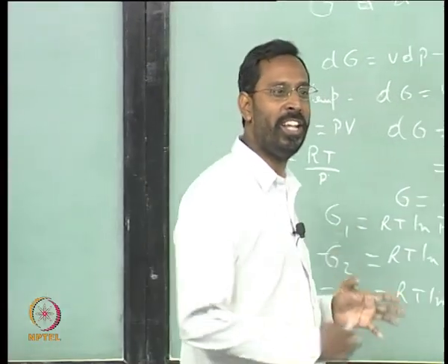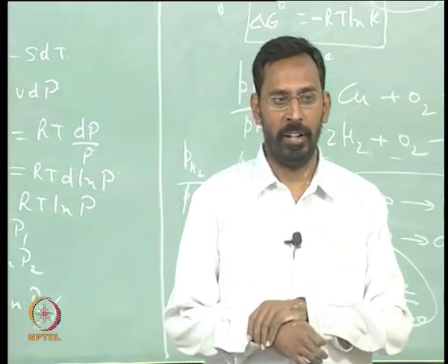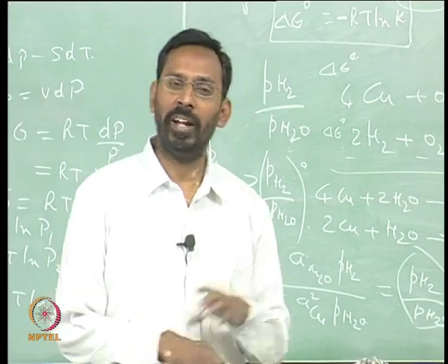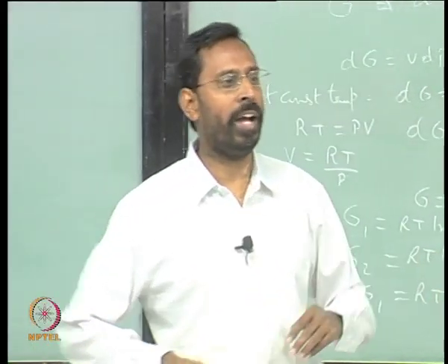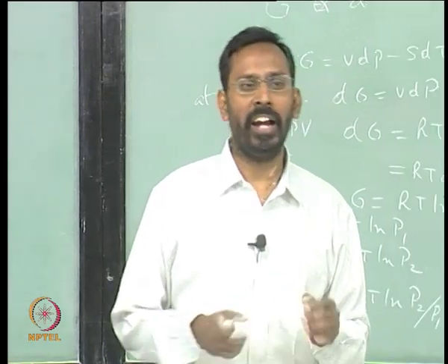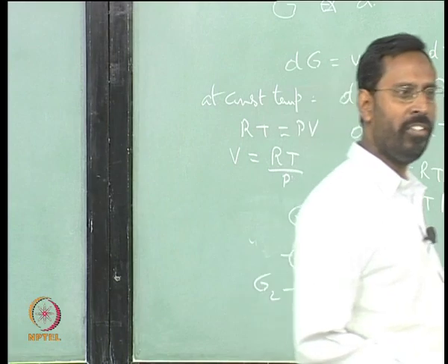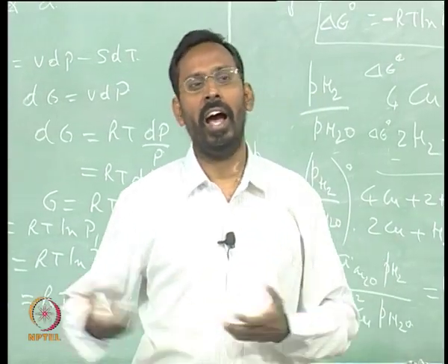And again this issue of activity equal to mole fraction also is not so easy. When is activity equal to mole fraction? When it is an ideal solution. So, if I am assuming it to be an ideal solution, and ideal solution works out only in very dilute conditions, whenever it is a very dilute alloy, then I can think of that.